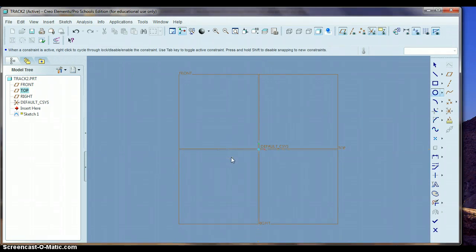So I'm going to draw 1 circle. I'm going to move over here on this other side and move my mouse out until I see a little red R pop up, which means the circles are the same diameter. So again, just keep moving your mouse out until that little red R pops up. Then I'm going to make a kind of like a triangle out of these and move my mouse on this vertical dotted line right here above them, and click and move my mouse until I see that red R pop up again, and then click. So I should have 3 circles kind of forming a triangular shape.